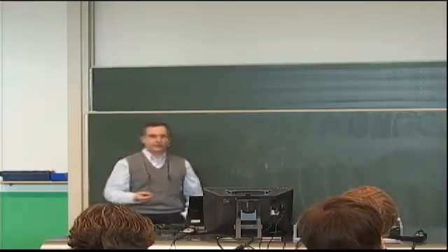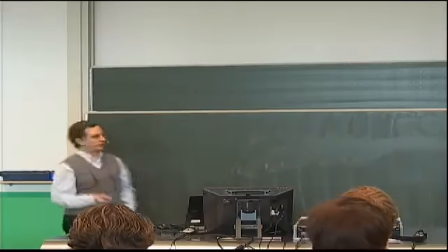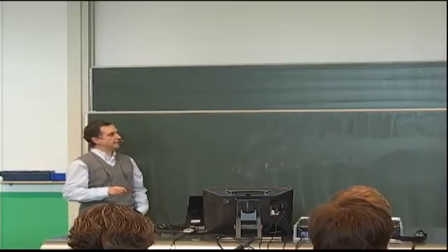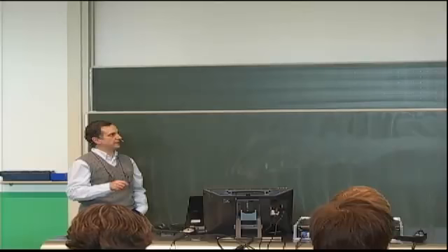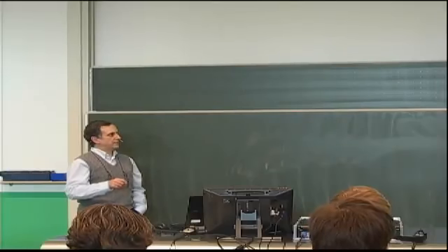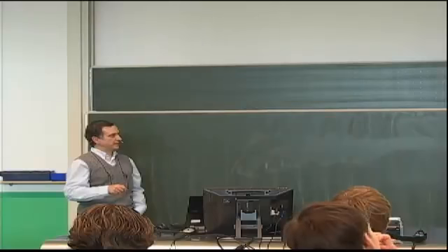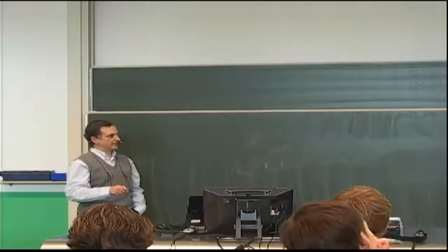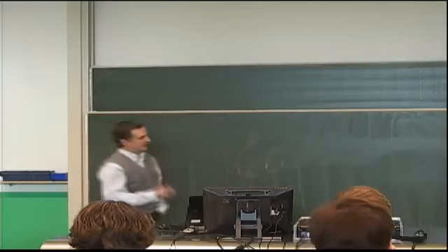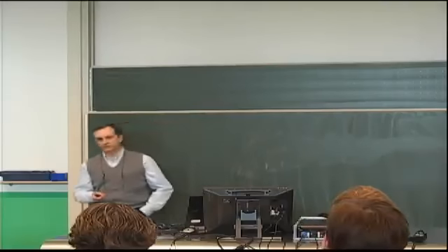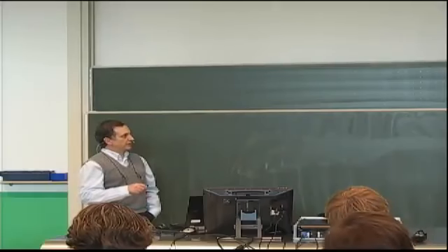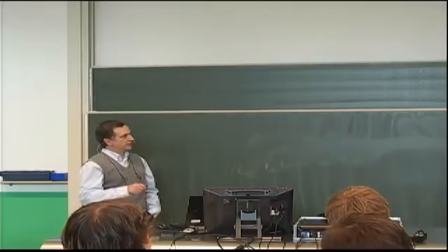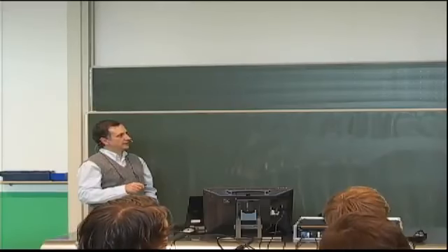Our first check or our first evaluation before we proceed has to do with to what extent we can reproduce at the top edge here this step stress. So it's 0, and then it goes to a constant value and then comes back down to 0. And this helps us to pick the number of terms, because obviously as you increase the number of terms, you will get closer and closer to the exact solution. But as long as we get close enough to this step distribution, or step function, then we don't need to keep adding more terms, because obviously computationally it takes time.